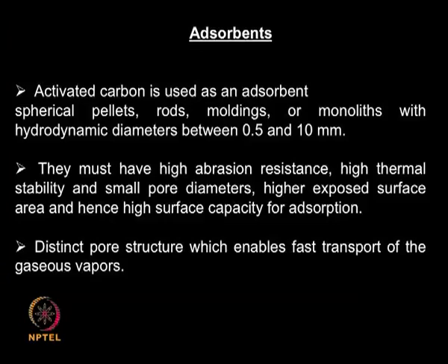So, when you move from smaller to larger particles, the surface area goes down, so the activity also goes down. If you use very high temperature for activating your adsorbent, sintering could be a problem which should be addressed as well. There are many adsorbents present in the market because adsorption is a very old, well developed technology, with products like activated carbon, charcoal, zeolites, silica aluminate and so on. These are widely used for a large number of gases, for liquids, metabolites and so on.